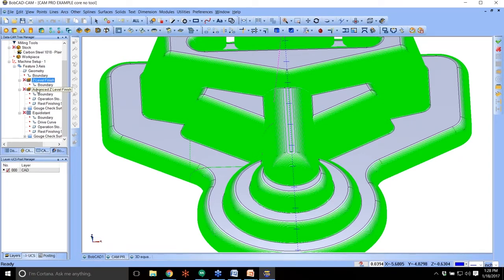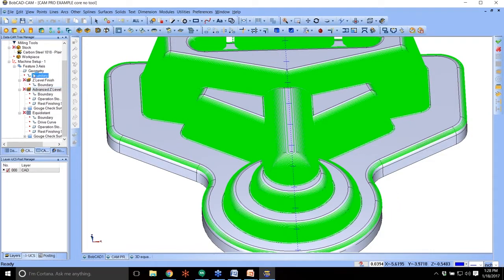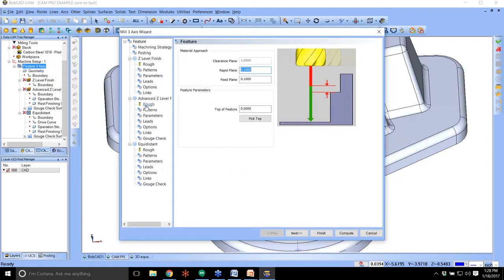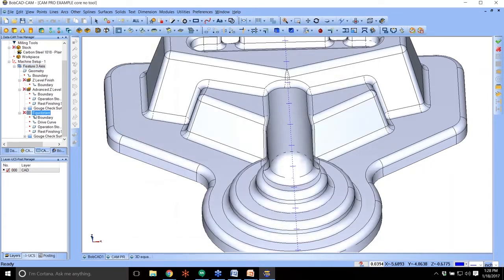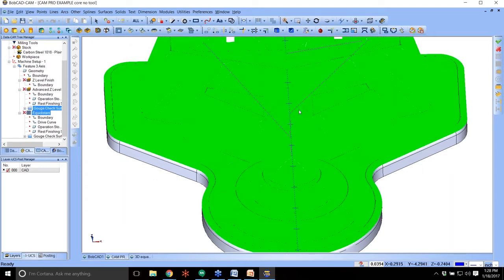So when looking at the toolpath and what you should use, sometimes it's better to go in because maybe I can get it to do this, okay? So what I could do is I could go in and you can mess with certain options in here, like adaptive depth of cut, to help compensate when that scallop gets a little bit bigger as it goes down the surface. You have those options that necessarily aren't available in another toolpath. So you guys can turn that option on, set a maximum step over distance, and then let it calculate and it'll help, okay?